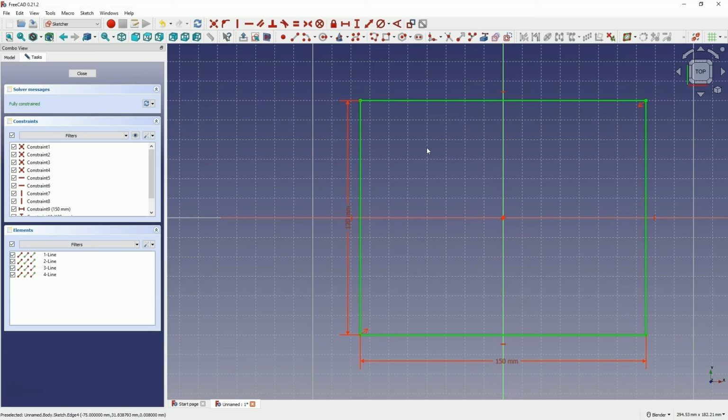At this point, if I accidentally grab some geometry, I won't change anything here. I won't change the shape or position of this geometry. And if this sketch were not constrained, if I accidentally grabbed the geometry, I could change its shape and position, which could later impact subsequent stages of the project. We should strive to ensure that the sketch is fully constrained.